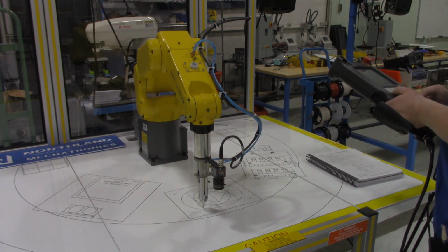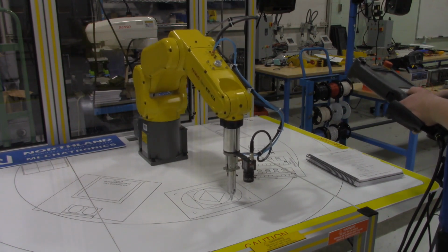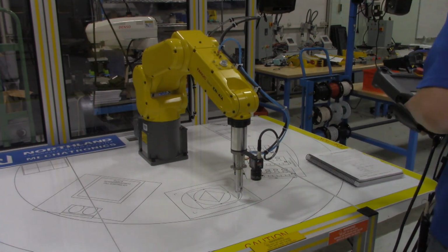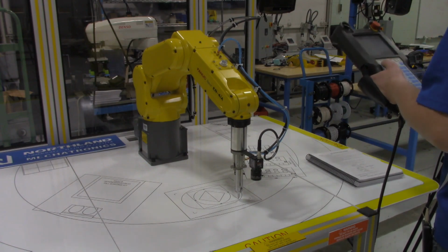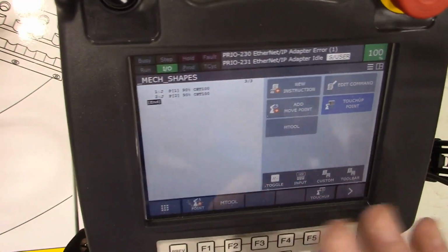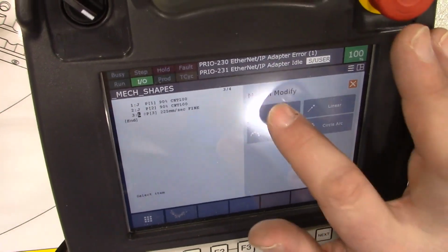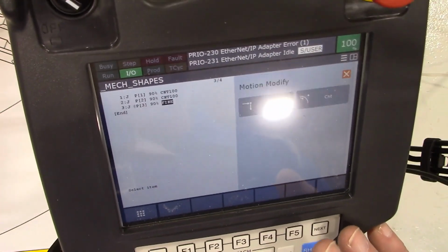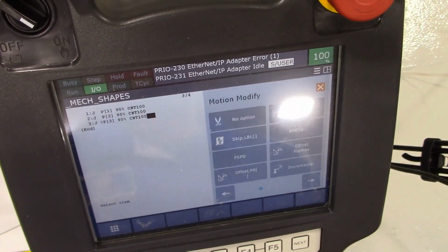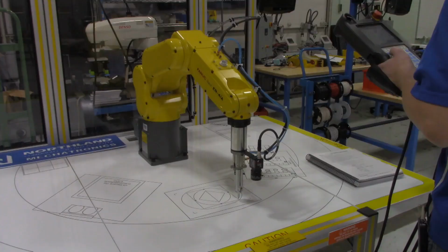And that should be a Y motion, Y positive. That's good enough. And back to the teach pendant screen. We'll do a shift point on that and change it from linear into joint. And I'm making all of these continuous. Okay, and back to jogging the robot.